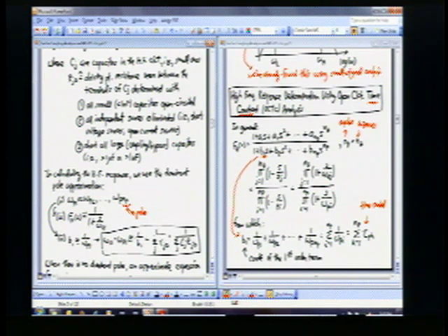We don't care that much. For frequency analysis, if you can get within 2 times of what that frequency is, you're good. You've done a great job with hand analysis. So what you're learning to do is hand analysis to quickly get the frequency response, and then you plug into something like SPICE, which will do a lot better job of determining exactly what that frequency is. That's the way you should do circuit design.